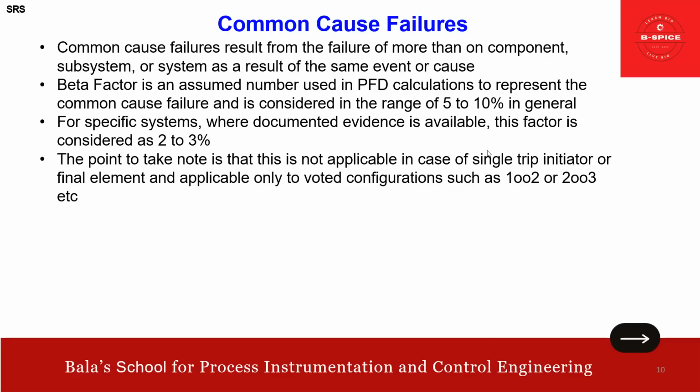The point to take note of is that this is not applicable in case of a single trip initiator or final element, and is applicable only to voted configurations. What is that? 1 out of 2, 2 out of 3, like that. That is the point actually.